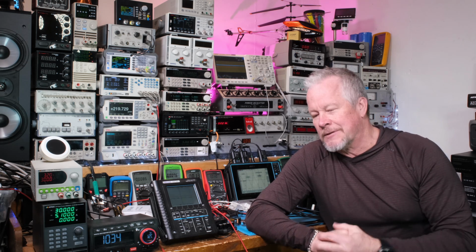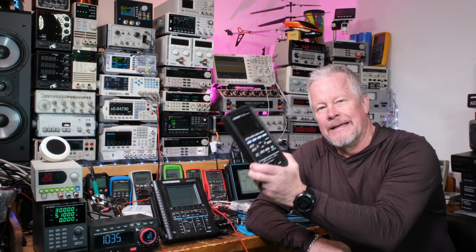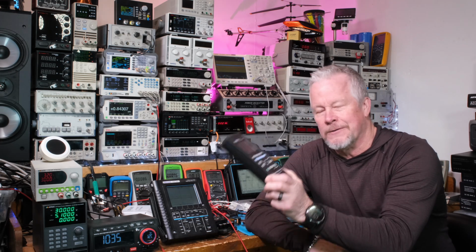Both components have parasitics of L's and C's, so it makes the curves not just a straight line for X of L or X of C, right? So if you're really trying to do a Class D amp, crossover, or any kind of filter, it's nice to actually look at the real curves, and you can look at different frequencies.